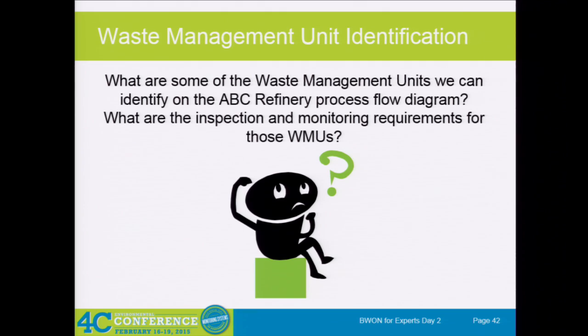The inlet concentration. Your clarifier tank is also typically an open top tank, so you would not do any monitoring there. How about vacuum trucks? You have both controlled and uncontrolled vacuum trucks. Actually, it shows them all controlled. So what monitoring would you have to do under your vacuum truck? What type of waste management unit is it? How do you classify them? Yes, you would classify those as a container, which requires both quarterly visual and annual NDE.